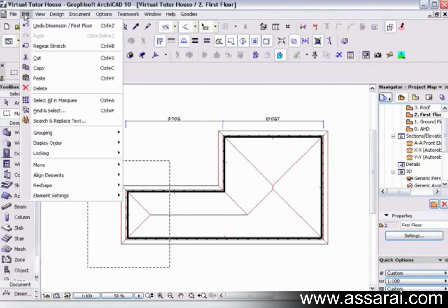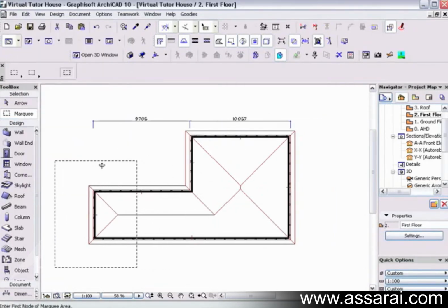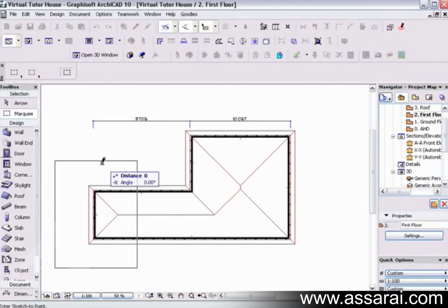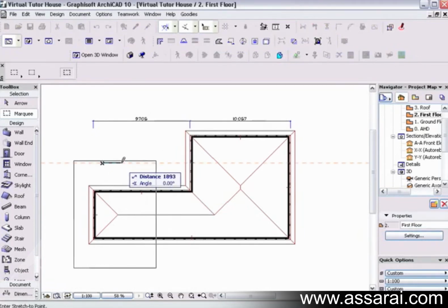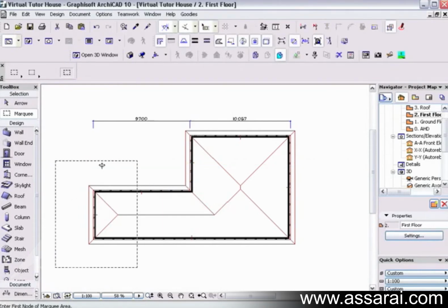Then we need to make sure that the grouping is off or suspended. So I just push Control H, left mouse click once, move that way until a guide comes up, and I'm just going to type 5mm, and we can see that now that's a nice round figure.